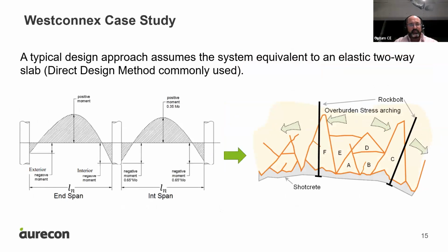But how do we design these in terms of flexure? The way this thin permanent lining works, you can make an analogy to a slab on columns. If you think that these rock bolts are the columns and your shotcrete, your sprayed concrete, is the slab, if you put it upside down, it's very similar. So the way that was typically designed until a few years ago in Sydney is that we use an analogy to slab design, and more commonly we also didn't want to complicate that much.